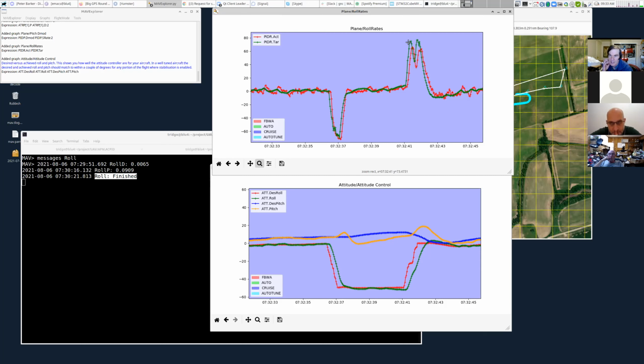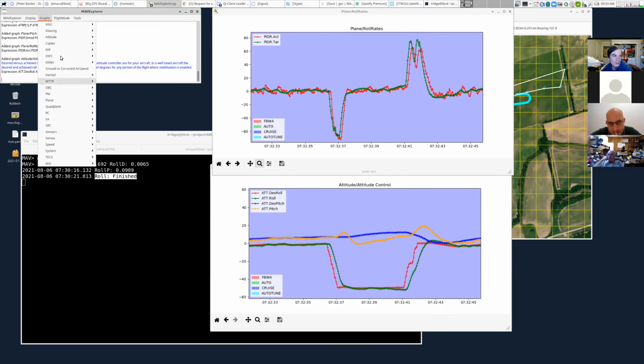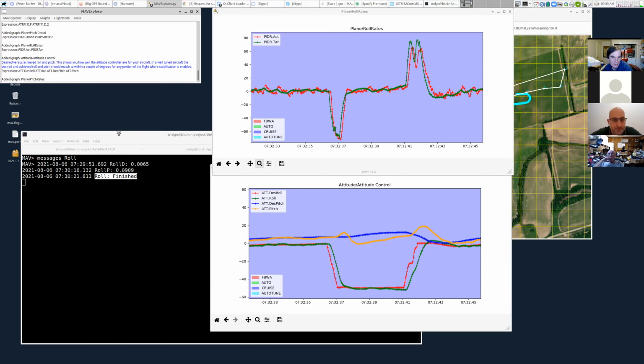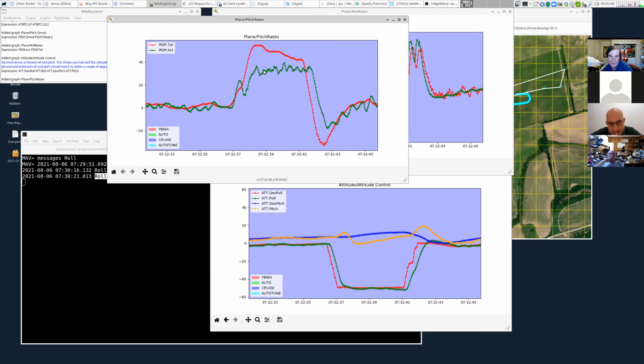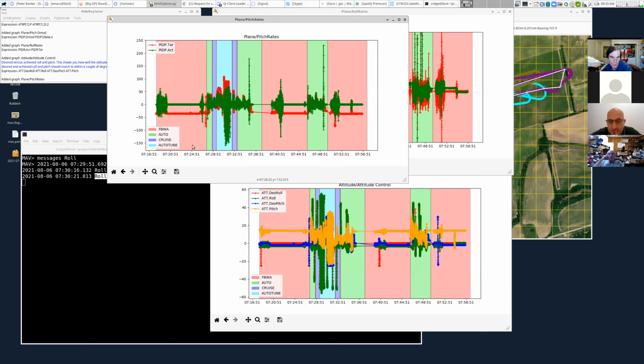Foamy aircraft tend to be a little bit floppy, and the linkages often are not quite perfect. But that's really a pretty good roll tune, right? We could have a look at the pitch tune and say, so we look at the pitch rates and we'll see, now he didn't do as large pitch movements here, but it's a little bit low. It's not quite achieving what he wanted.